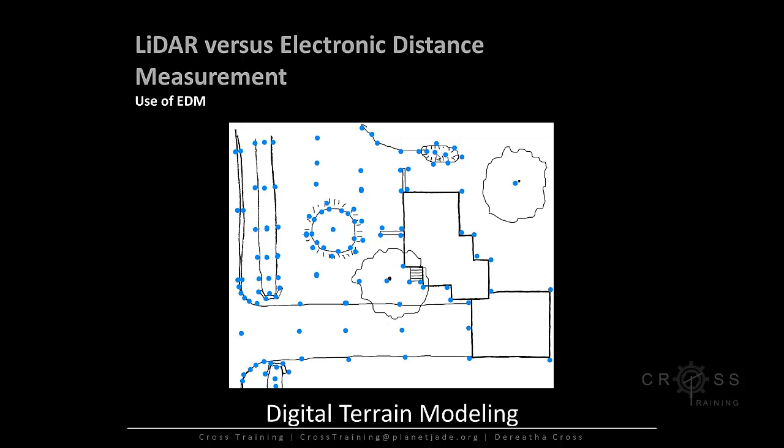While we're at it, we'll get the elevation of the pond. We'll maybe get the major drainage line. Maybe we'll do the same thing with the ditch, top of the ditch, the middle of the ditch, the bottom of the ditch. Maybe we'll also get this curb information over here and this driveway. So when we go to build out this terrain, it's going to be very, very detailed. We're going to see that over here it's really high and over here it's really low. There's a mound here in the front because this was sampled.